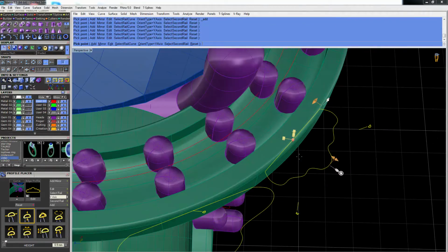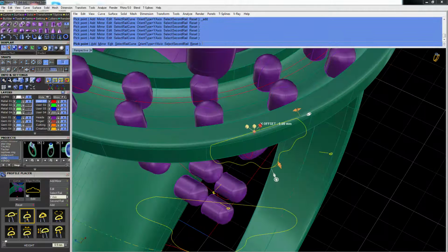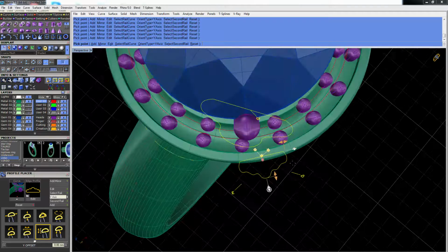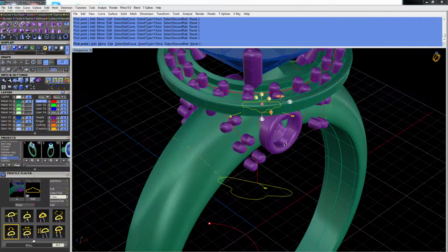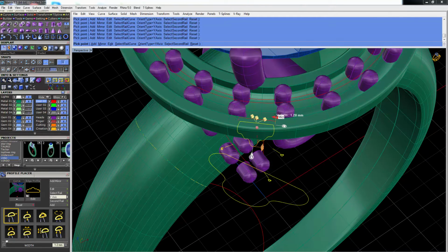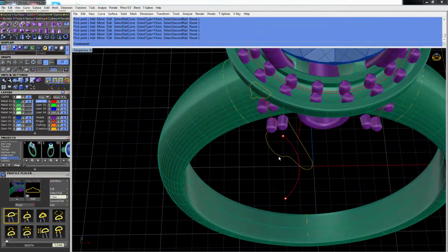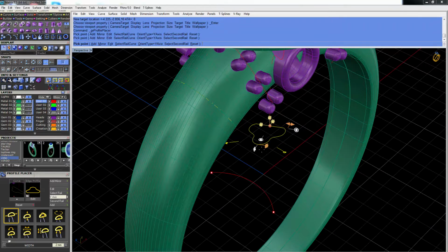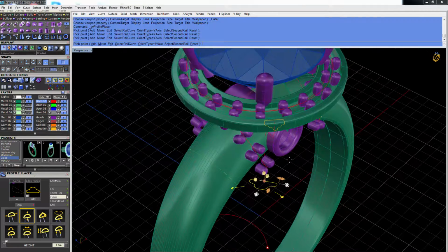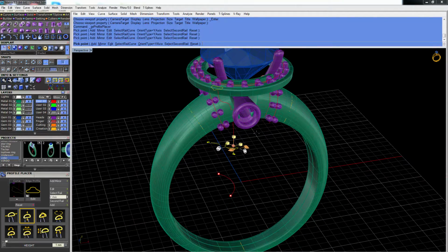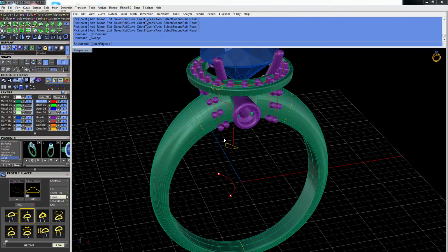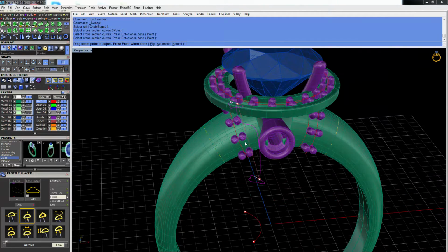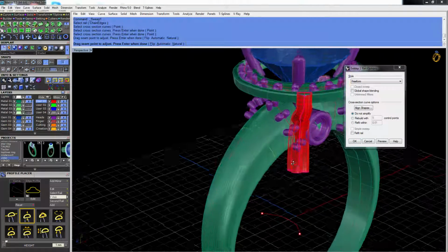Okay, and I'm gonna put it slightly that way. Okay, so it's slightly into the halo. Might be too big. Yeah, something like that. And of course this should be much smaller. F6. I'm gonna make it slightly bigger because I want the claw to be slightly wider on the bottom. Okay, so now I can go to surface, sweep one rail, touch the rail, that's one profile and another profile. Let's see how it looks. Just make sure that the arrows are both pointing in the same direction. Well, not bad.